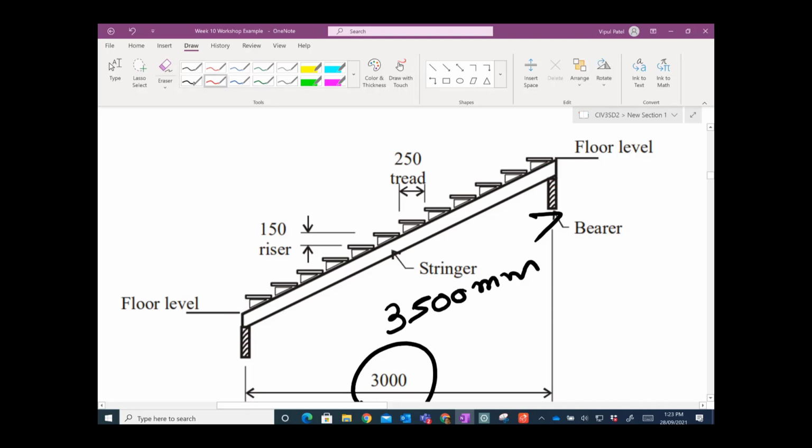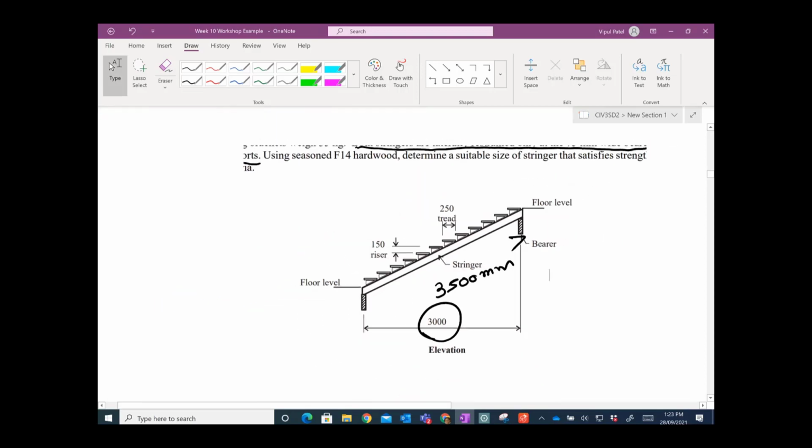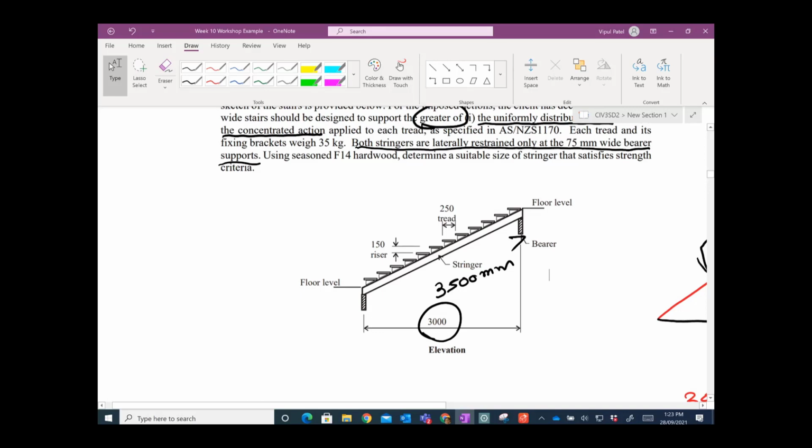Not like you just have these stringers and you have them just sitting like this. No, it will have a full restraint, otherwise it is just going to rotate, you know what I mean, from one end. Just slide the stringers on, just sitting on top of it. So you have a full restraint there. It is not laterally restrained on that end, you see.